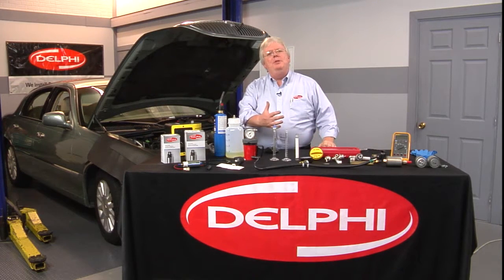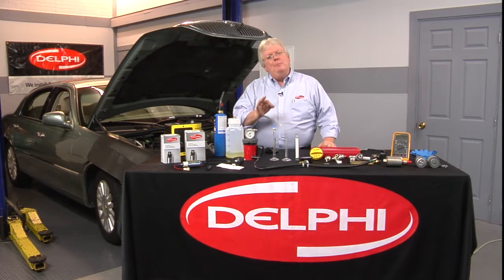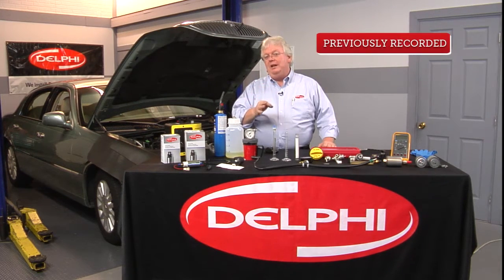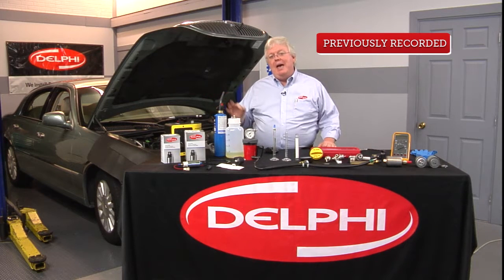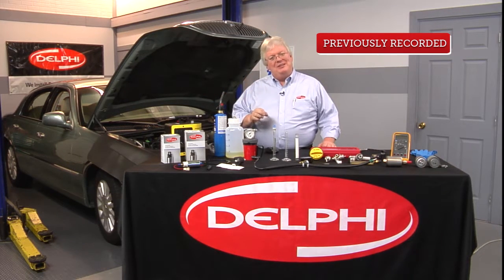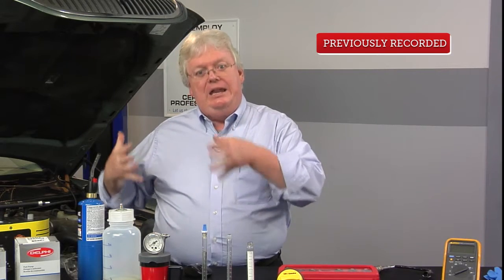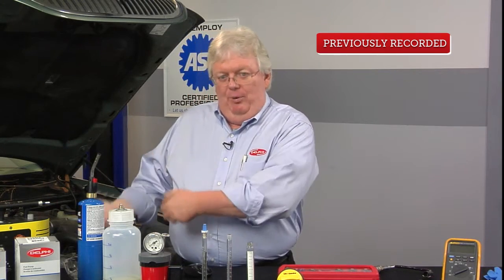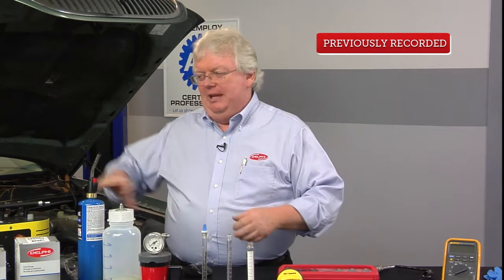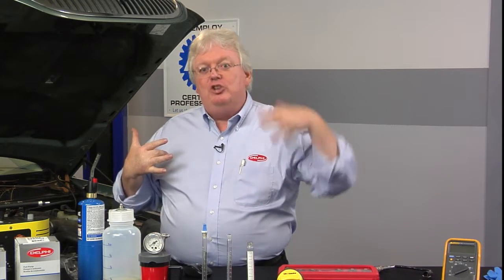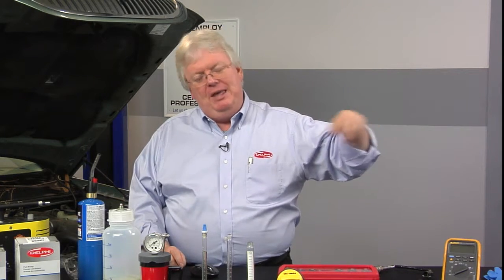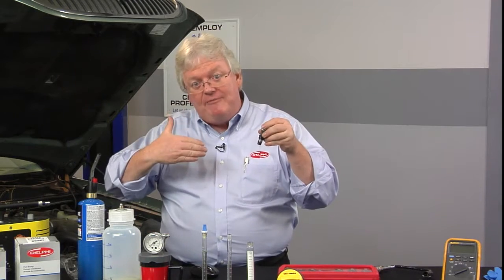But it could be something that's normal, like onboard diagnostics, OBD2, running not an evap leak test, but an evap canister saturation test to see if the canister indeed did store vapors, and we pull the vapors in, turn the purge on, leave the vent open, pull some vapors out of the canister, and as we use them in the engine and don't compensate, assume we had something to burn, we just let the base pulse width remain the same, and we pull those vapors in addition to the fuel spray of the injector, we have evap vapors.